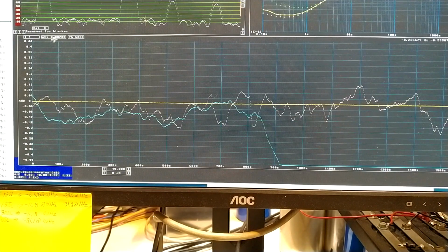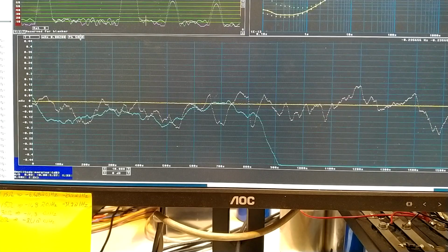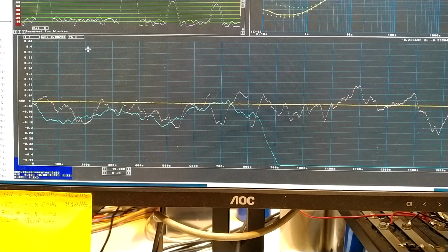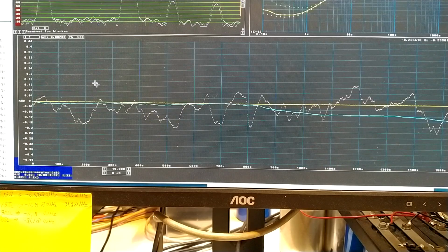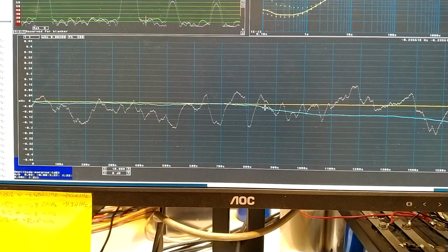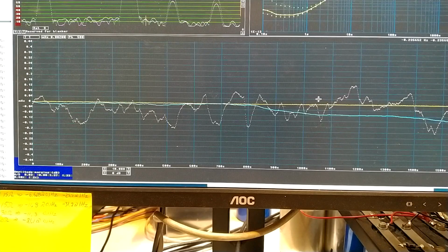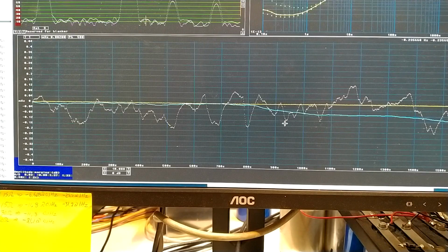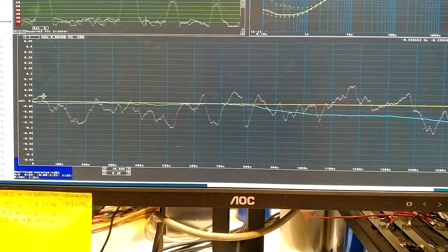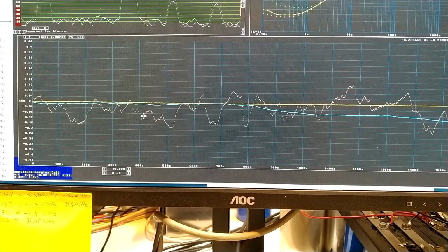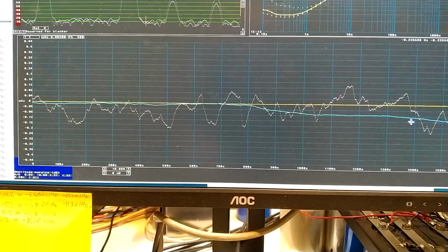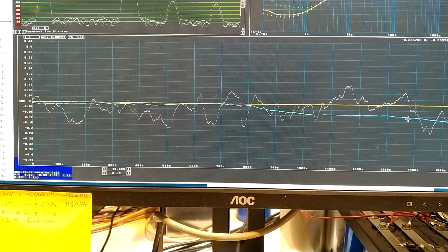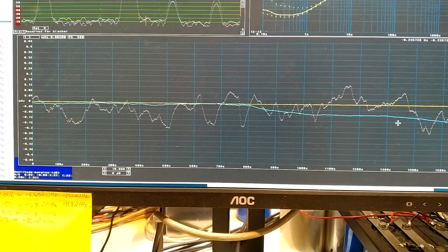And I have to reduce the sensitivity. It is now 5000. I make it 500 instead for the phase. And then you can see very clearly something happened and the phase is drifting away slowly. But that isn't causing oscillations of the kind that I saw in this section. It's a frequency drift that is slow. So I will leave this running for a while and then come back.